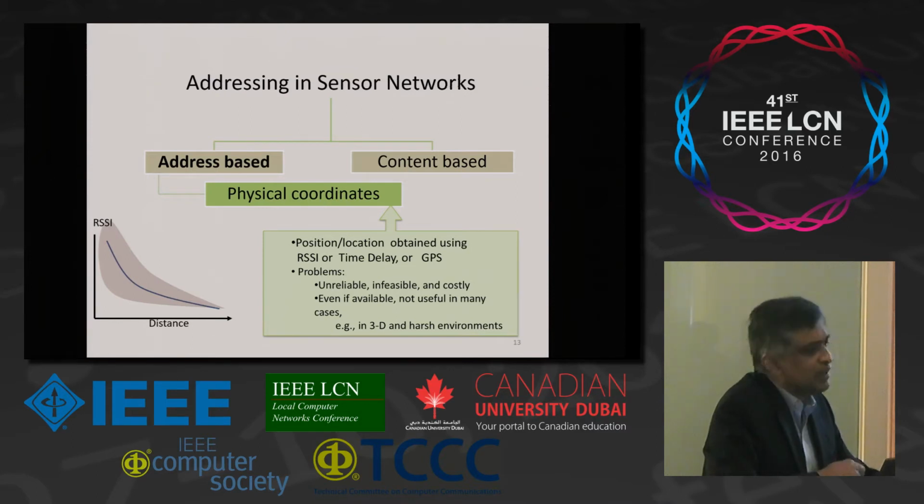Right. GPS is not available everywhere, especially in these harsh environments that we are talking about. If you use GPS, it's going to significantly increase the cost. Time delay, well, to get time delay, in this case, you have to synchronize the clocks. Right? Synchronizing clocks is a more difficult problem than getting the time delay. So you can use it, but again, scope is limited.